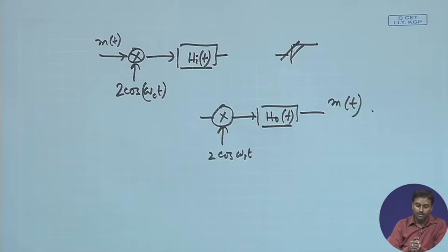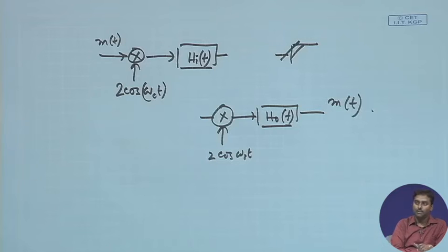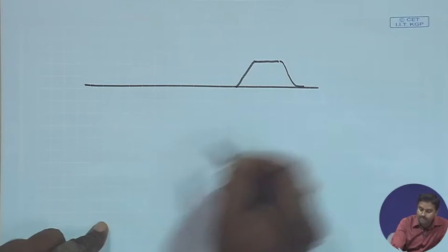Okay. So, this is actually the VSB-SC modulation and demodulation. It is pretty simple, the only thing is that this filter has to be carefully designed, the way we have demonstrated in the earlier case. So, that has to be very carefully designed, so that H(f + fc) and H(f minus fc) give me 1 in all the places. Only thing is that beyond that it is not that much required. So, whenever you are designing that filter, you can always say that I need to have this, after that it can have any roll off.